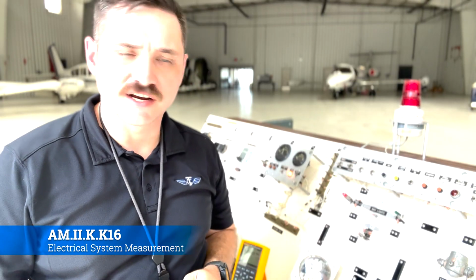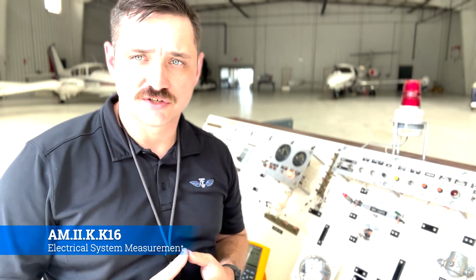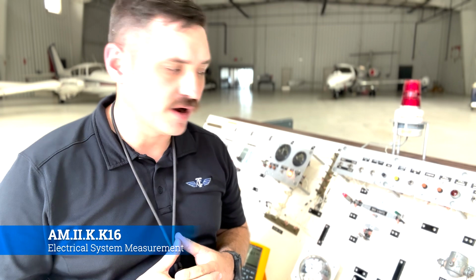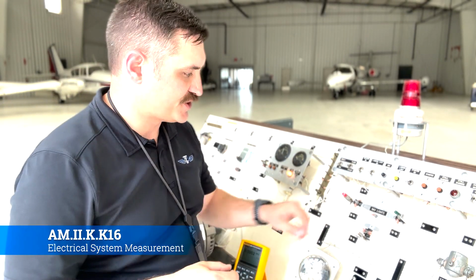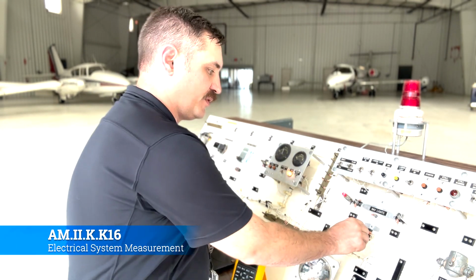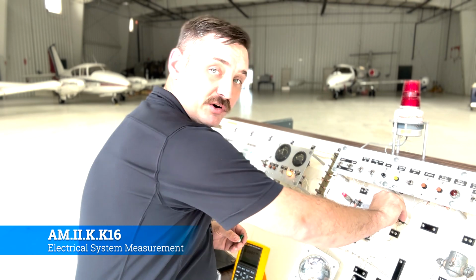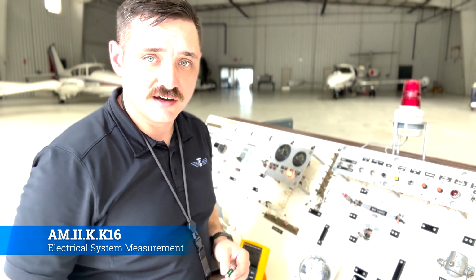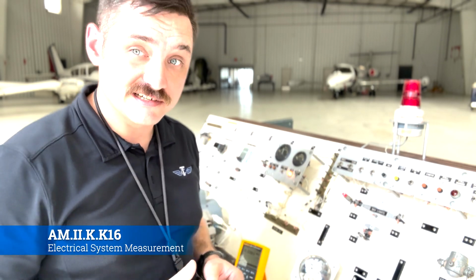Okay, in this scenario, our right nav light is not working, and so we're going to do some measurement to try to test and see what's going on with it. Now, the first thing that we would want to do is simply just change the bulb out. So we notice that this bulb is the one in question. We know that this one is currently working. We put the working bulb back into the socket that is not working, and it doesn't work. So leading us to believe that it's the socket.